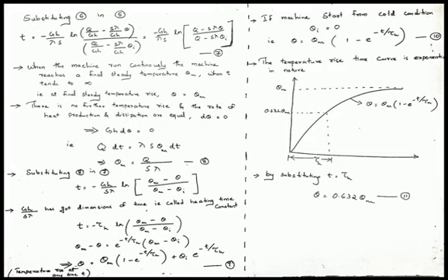So theta I's value will be 0 because theta I is the term which is indicating the temperature rise during start. So in this expression you will be substituting theta I as 0 and you will be getting the expression for theta is equal to theta m into 1 minus e raised to minus t by tau h. You can indicate as equation number 10. You are going to obtain the temperature rise time curve from this relation. So while obtaining this curve, you will be getting it as exponential in nature. Y-axis indicates the temperature and x-axis will be indicating the time period t.